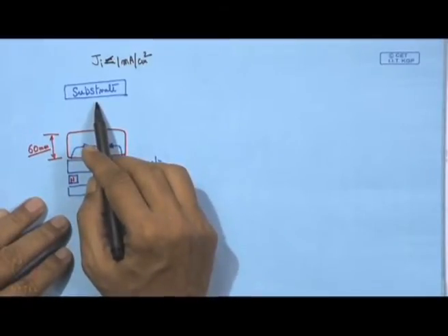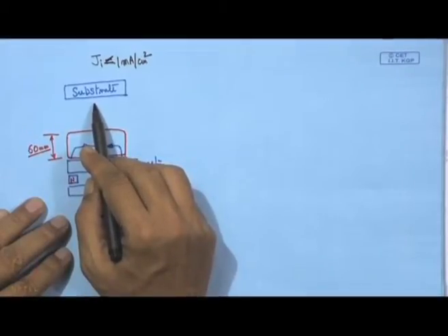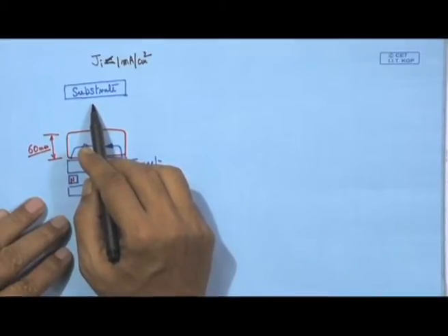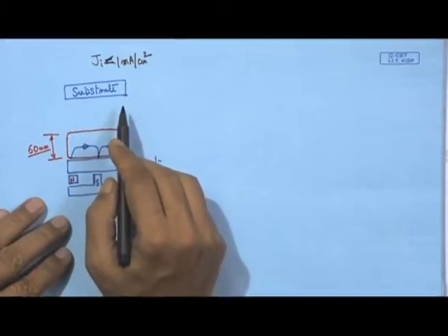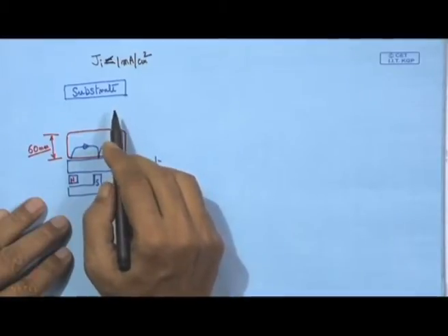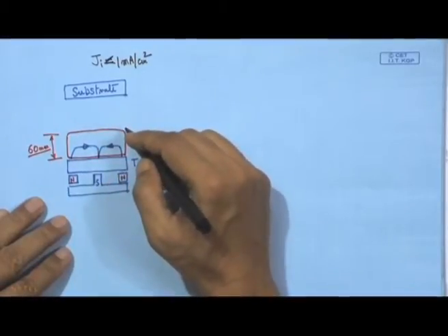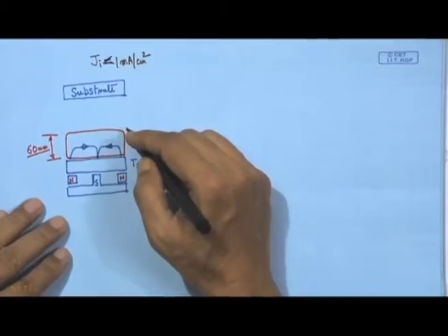As a result, this low plasma density cannot produce a well dense film over the surface. The coating will lack mechanical properties like hardness, cohesion and adhesion.